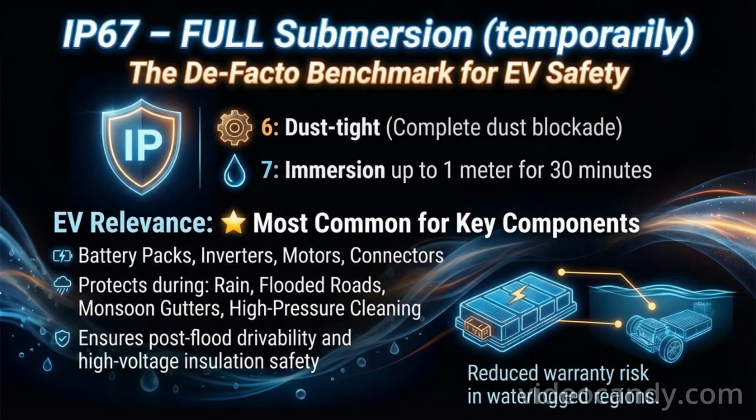IP67 is the immersion-rated, temporary submersion standard rating. IP67 certifies complete dust blockade and safe immersion to 1 meter for 30 minutes, the de facto benchmark for EV battery packs, inverters, connectors, and motors. The spec covers flooded streets, monsoon gutters, and high-pressure cleaning without extra covers. By validating that seals survive modest hydrostatic pressure, OEMs assure customers of post-flood drivability and protect high-voltage insulation, reducing warranty risk in regions prone to seasonal waterlogging.